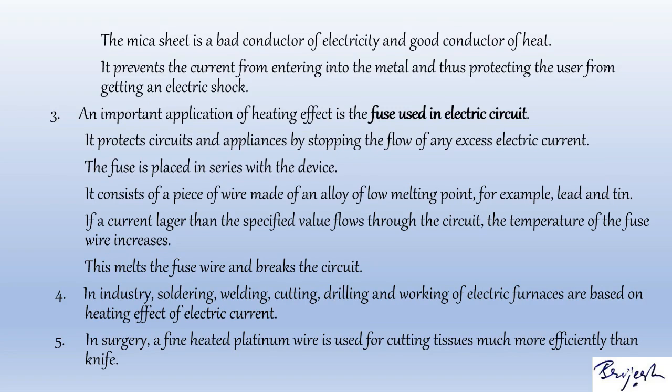If a current larger than the specified value flows through the circuit, the temperature of the fuse wire increases. This melts the fuse wire and breaks the circuit. The fuse wire is usually enclosed in a cartridge of porcelain or similar material with metal ends.